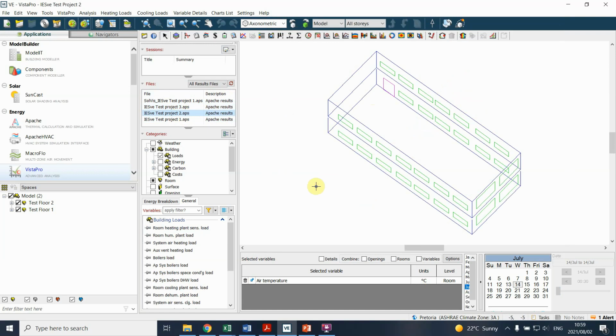So this is a way for you to start playing with the types of window openings and what the implications would be. I think you will realize that there are obviously limitations to only using naturally ventilated buildings if you have a high occupancy density. If it's for houses, we often know it works quite well. But there are ways of ameliorating the indoor temperature through air conditioning systems or night cooling and so forth. All that you can start modeling using the same method. My advice though is always start with the basic model so you know what typically happens, and then start changing so you make that comparison in the end.